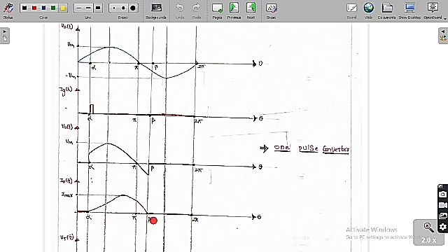As the current would have to become negative, but a current cannot be negative in a thyristor, the current will be 0, meaning open circuit, and the thyristor is going to face the negative voltage. Because of that, it acts like an open circuit, so the current will always be 0. As the switch is open, the load voltage is also equal to 0. So from here to 2 pi, the load voltage and the load current are both 0. You can see clearly that in 0 to 2 pi, only one pulse is present, so it is called a one pulse converter.